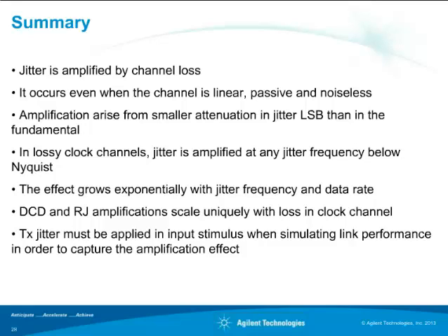We found that DCD and RJ amplification scale uniquely with loss in the clock channel, and when simulating a linear channel performance, it is critical to apply Tx jitter in the input signal in order to capture the amplification effect.